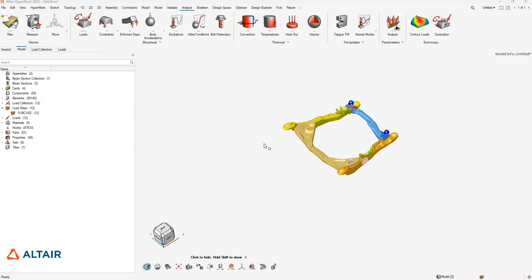But today's topic is how to set up a fatigue subcase using Altair HyperMesh that can be solved by the OptiStruct solver. Setting up a fatigue subcase is like any other subcase, like FRF, static, or random subcase, which can be very advantageous when you are optimizing for fatigue responses such as damage or life. So you can create responses and optimize using any structural optimization problems.